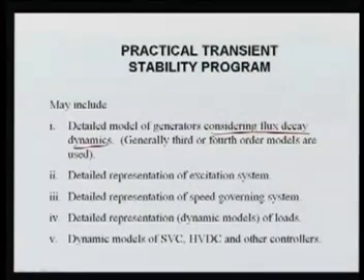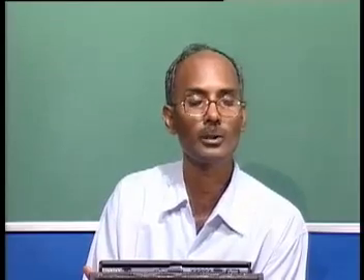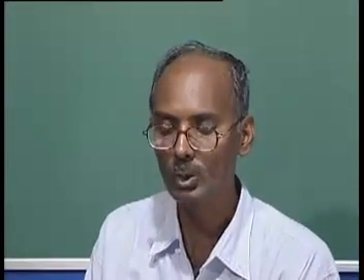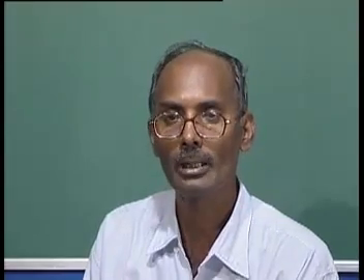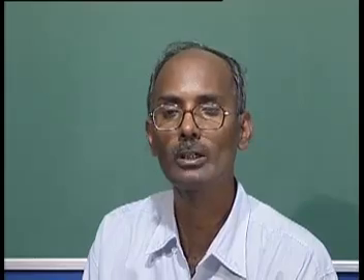Also we have to represent the excitation system in detail. Different types of excitation systems are used for different types of machines, so that will also be included in your practical transient stability program, because it is not only the classical model, where we never model the excitation system and only model the machine with its inertia.